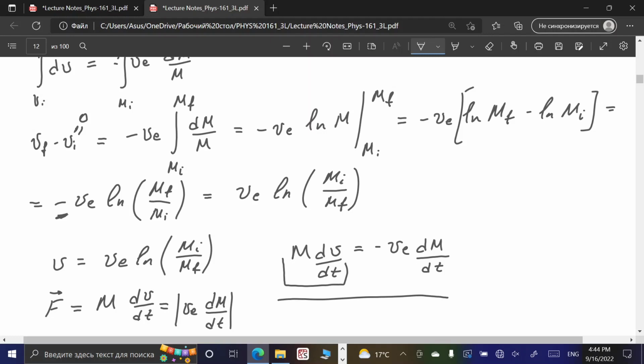And since we want to provide both very high temperature and very high burning rate, in order to protect the concrete construction of the launching table for the rocket, thousands of tons of water are provided during this very short time when these exhaust gases are still in contact with the concrete table. They pump a lot of water in order to protect the walls of this concrete table from being damaged by these extremely high temperatures and extreme pressure provided by the very high burning rate. Otherwise, if you don't provide this kind of buffer layer created by a huge amount of water, this concrete table, regardless of the quality of the concrete, will be damaged, and you will have an extremely expensive rocket launch because that will be just single use, which is not acceptable in the space industry.